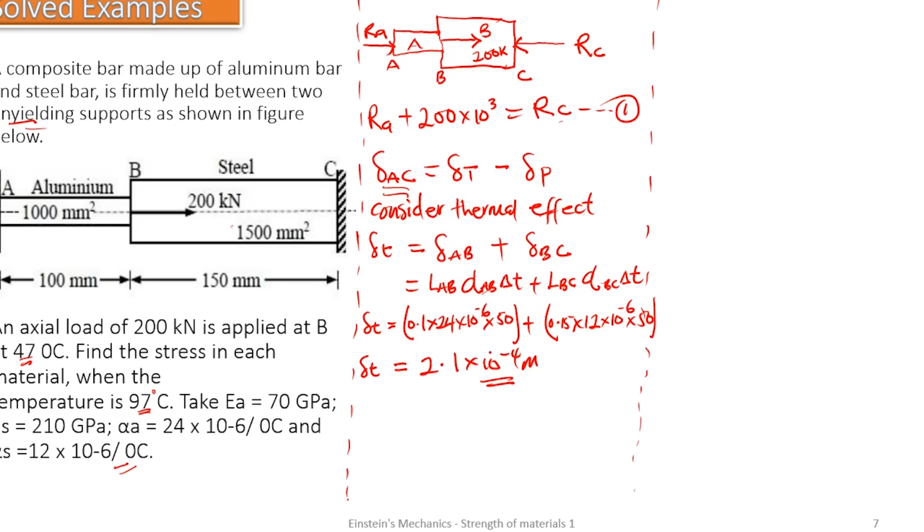So only the temperature is going to deflect this entire bar by this amount. So suppose the question asked, or there was only temperature effect on this bar. This will now be the corresponding what? Deflection. There wouldn't be any effect of force if the question hadn't brought this 200 kilonewton force.